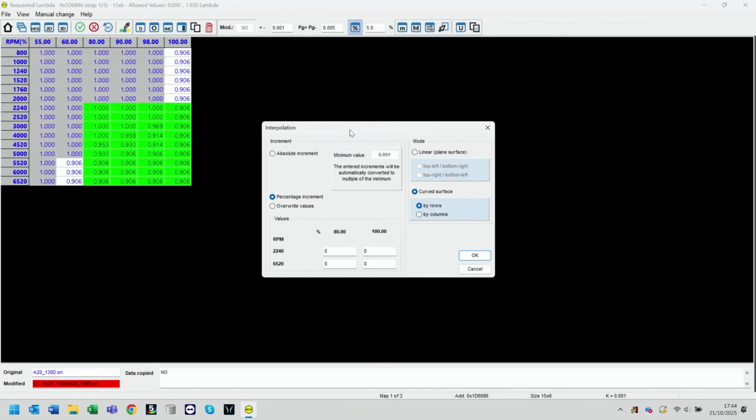our interpolation. Now, on our interpolation, we've got the ability now to start reducing these values slightly. So if we're looking anywhere from around about a 5 to 6% reduction on our bottom right-hand corner, that's going to take us down to around about 0.86, 0.87 stoichiometric value, so on our Lambda, which is about 12.7 AFR for those that are working in AFR scale on there.